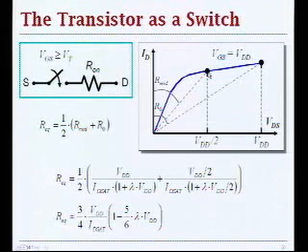So all you need to compute is basically the voltage over current ratio, and average out these two points. And you end up with a simple expression like this, that your equivalent resistance is 3/4 VDD over IDSAT times 1 minus this term that you can oftentimes neglect to a first order.